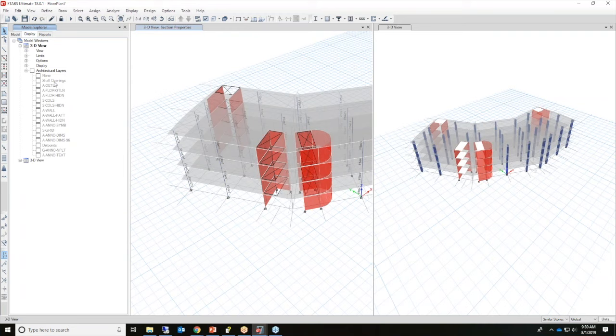So when you're generating your columns, just make sure that they are in the specific column layer, and break up the model individually into those specific elements, such as walls, slabs, area objects. You can see other things that have been included here are grids, text. So the more detailed you are in breaking up the model into those specific layers when generating the DXF file, whether it be in AutoCAD or MicroStation, the easier it will be to generate this model here in ETABS with these layers.